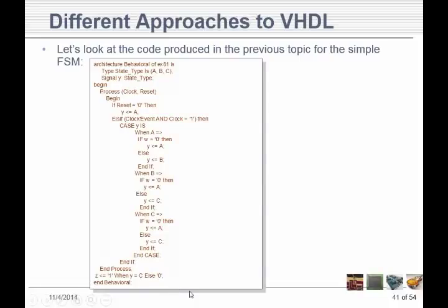I think you guys are finding that out on your flip-flops, right? You can't say something like Q is equal to not Q. Won't work because Q is either an input or an output, and if it's an input, it can only appear on one side of that assignment statement, and if it's an output, it can only appear on the other side of the assignment statement.